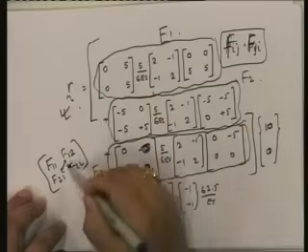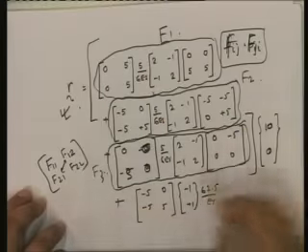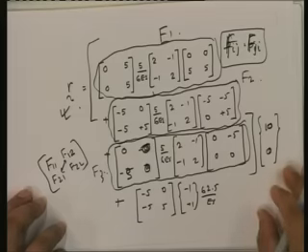Now think about this. Displacement at 1 due to a unit load at 2 and displacement at 2 due to a unit load at 1. Shouldn't they be the same? Which law is that? The Maxwell-Betti reciprocal theorem. Okay? If you look at that, then automatically these two are equal to each other, and you will see that this is also a symmetric matrix. Okay? A symmetric matrix is one in which the transpose is equal to itself. That is what a symmetric matrix is.